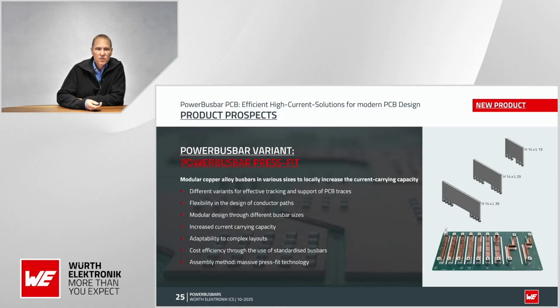So you also have adaptability to complex layouts, and we say this new product will have cost advantages, because these bus bars are standardized and we can produce them in higher quantities. So we see cost advantages for you. And the assembly method is the proven massive press fit technology, which is very reliable and used for many applications.